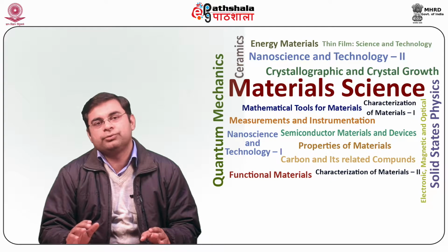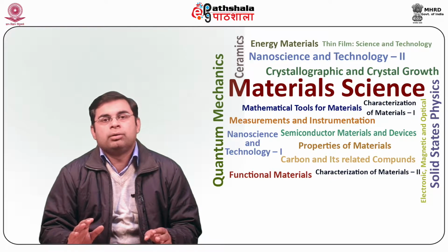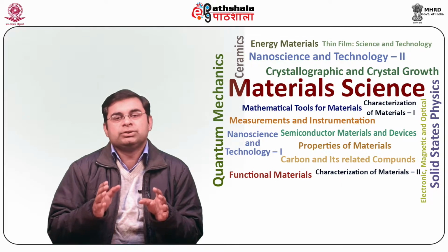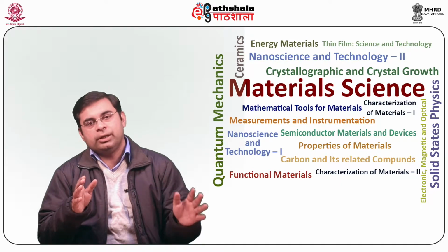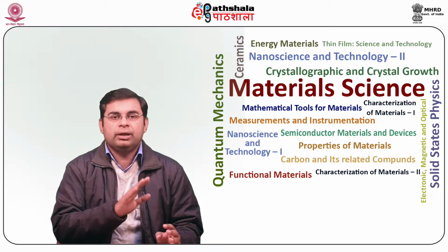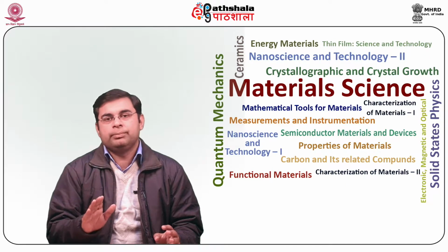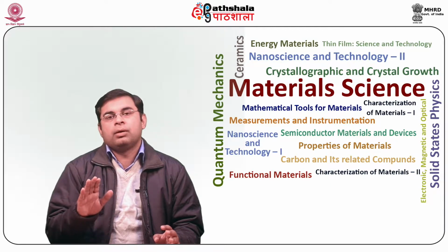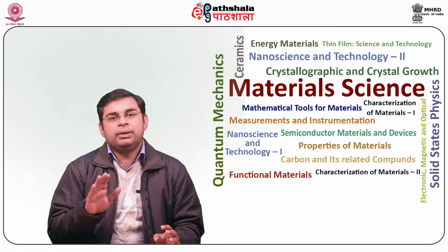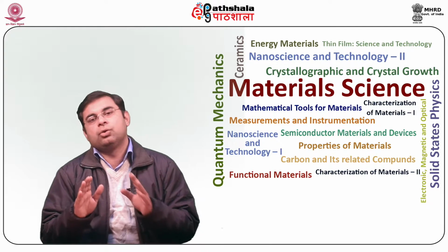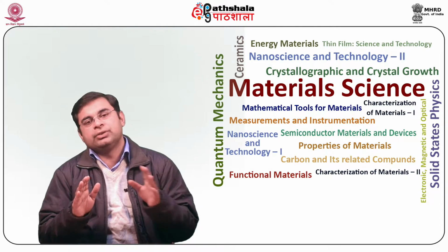When the semiconductor interface is formed, this energy offset phi Bn naught, also known as n-type Schottky barrier height, causes a potential energy barrier which acts as a rectifier such that electrons can readily flow from semiconductor to metal, while electron flow in the opposite direction is difficult. When the semiconductor in contact with the metal is doped p-type, the energy gap between the Fermi level and the VBM, marked as phi Bp naught, becomes the energy barrier, that is p-type Schottky barrier height, that governs the whole transport across the metal semiconductor interface.